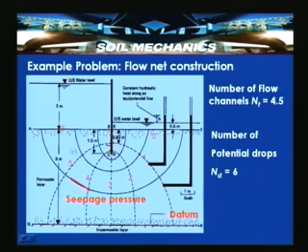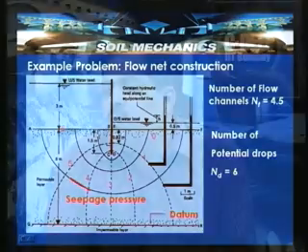So, the first and foremost thing in constructing flow nets is that one has to draw this cross section to a scale on a graph paper.